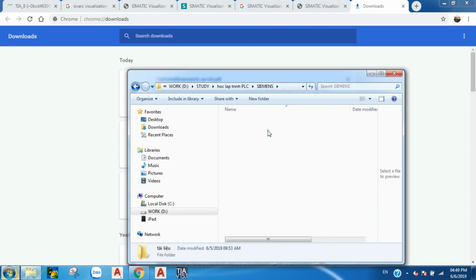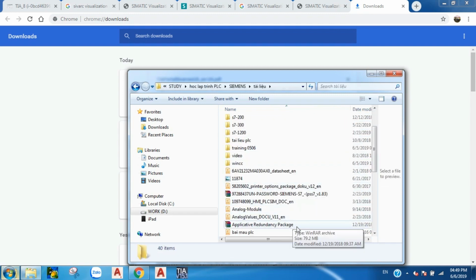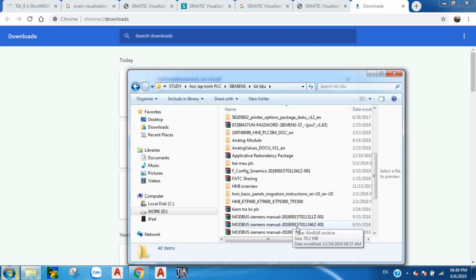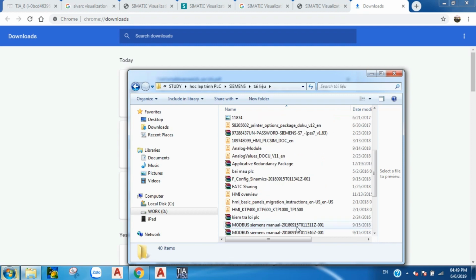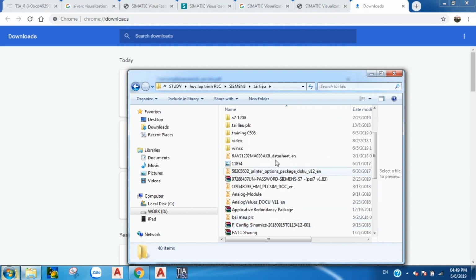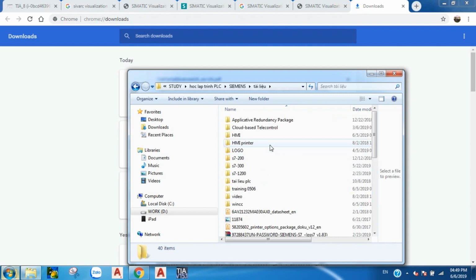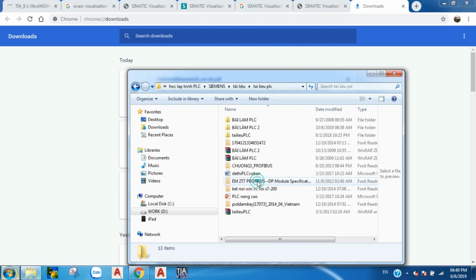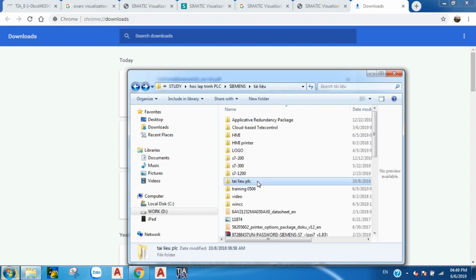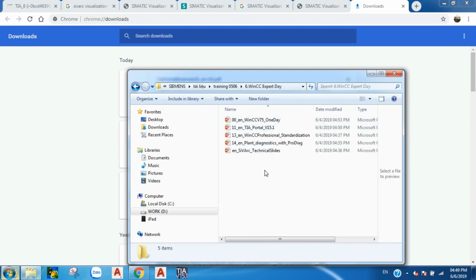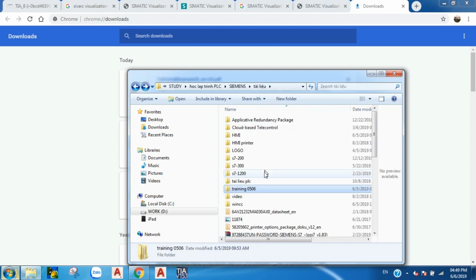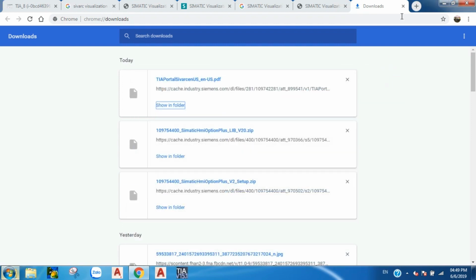Okay. The master copy is still the same for my screen, so still the same as the template screen. But in this case, I don't want to use the layout field tank. I use trend. That's all I want to do, and I can start generating the screen. So I'm going to go back to WinCC Runtime Professional, right click, and generate the visualization file.